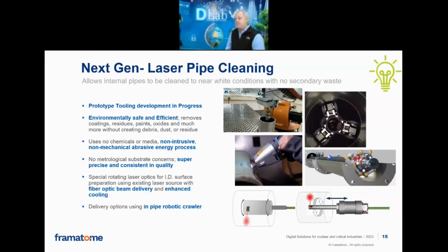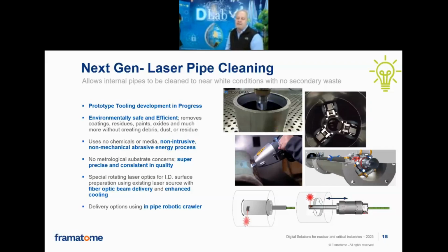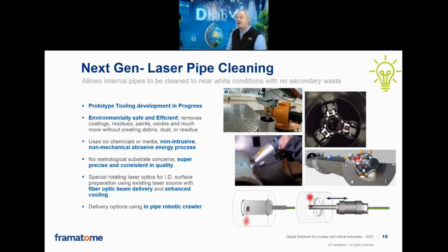The other thing that we looked at with this technology was that the Department of Transportation in the States did a lot of testing with this. So does the operator come into environmental conditions with these lasers that could affect them from a health and safety standpoint? It has a small vacuum head that's built into this type of technology, and it actually does very well at evaporating the contaminants. So we were able to use this technology to safely and efficiently clean the pipe without affecting any of the environmental standards around that right now.